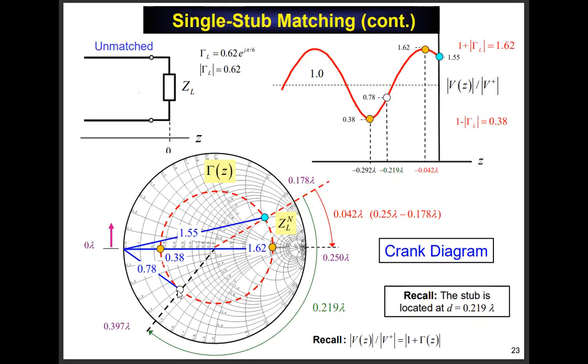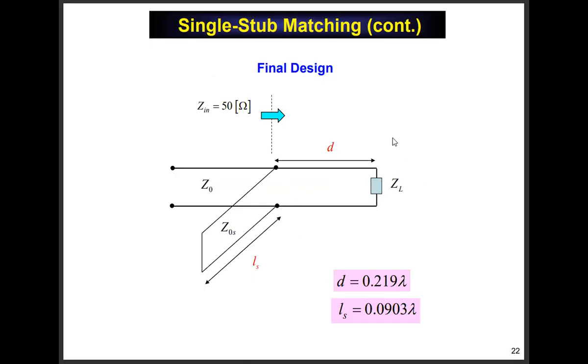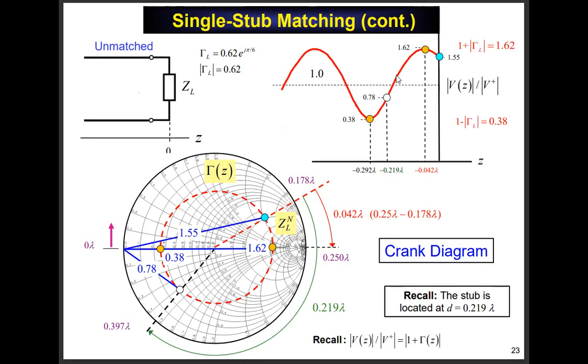You get out your ruler, you measure it, and it comes out to be 0.78. So right here is where we're going to put the stub. So this red plot doesn't keep going, because that's if you didn't have the stub. We're really going to put the stub right there. But the stub is not changing anything in this region right here. So the red plot here is good down to this point right here. And then all this has to change, because now you're on the system that actually has the stub.